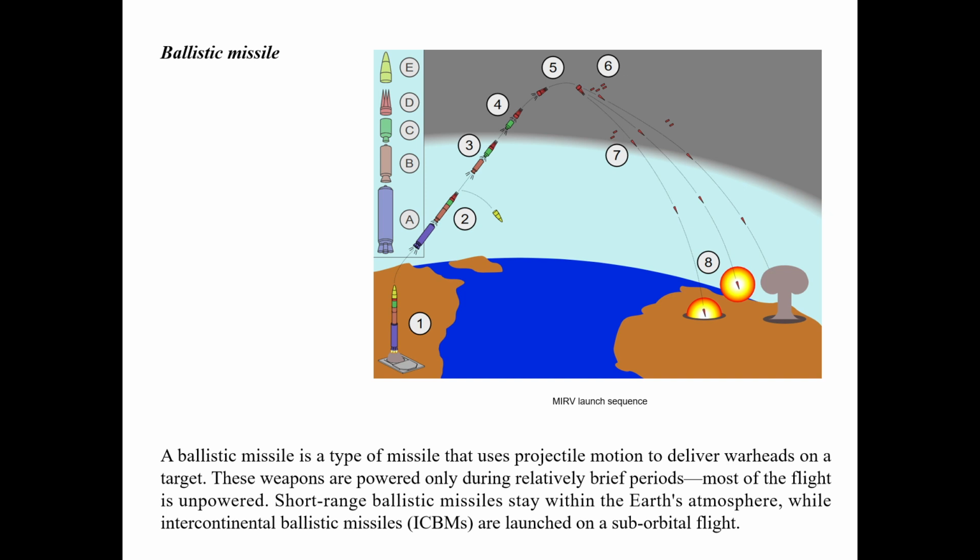So basically, the given figure shows MIRV. First I'll come to a ballistic missile. A ballistic missile has a single warhead, and the first few stages, like the booster stage and the solid and liquid propellant stages, will take the warhead to a peak position outside the atmosphere, and then it will lead to a free fall. During free fall, the terminal velocity will reach something like Mach 15 to 20.